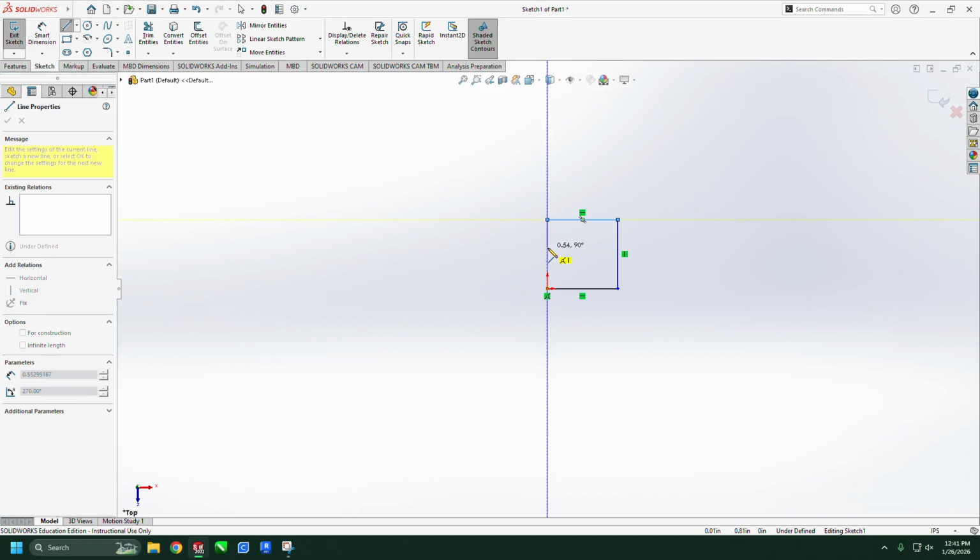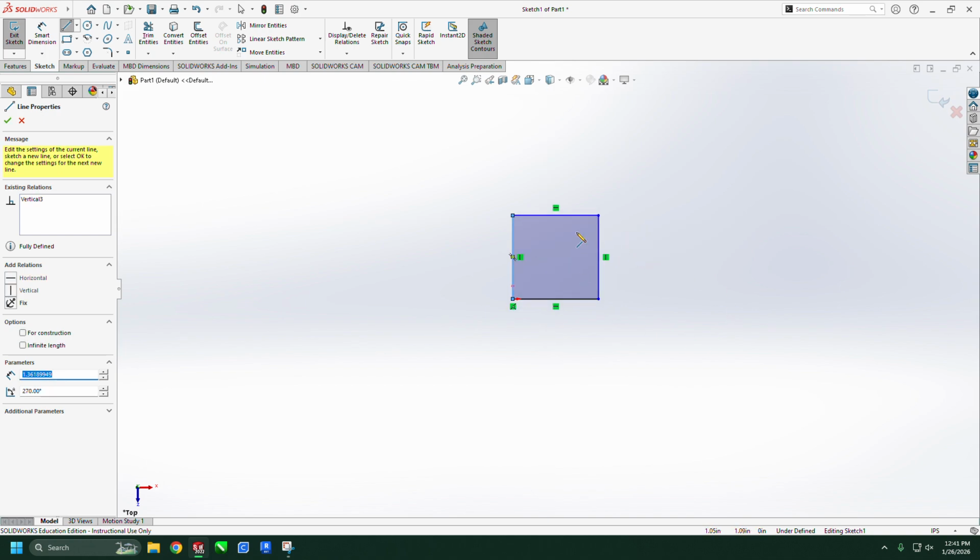So I'll click. And then when you draw here, you must form a closed loop. None of your lines should cross at any point. So if they cross, it will not work. So I'll go to where my starting point is and click. Notice when it's a completely closed shape, it will fill in shaded. Now at this moment, I drew the generalized shape of what I'm drawing.